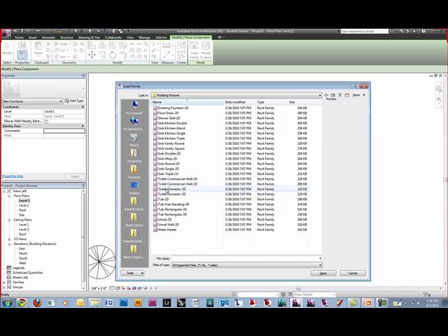Plumbing fixture is actually, I originally thought it was talking about plumbing components, like pipes and stuff. Completely different. But some of this stuff probably shouldn't even be in here. Like drinking fountain, these 2D objects are almost useless, especially if you're going to show a rendering. If you just need it for a floor plan, the 2D objects work fine. But if you go to render that space and you place 2D objects, nothing's going to show up and you're going to be pulling your hair out trying to figure out what happened.